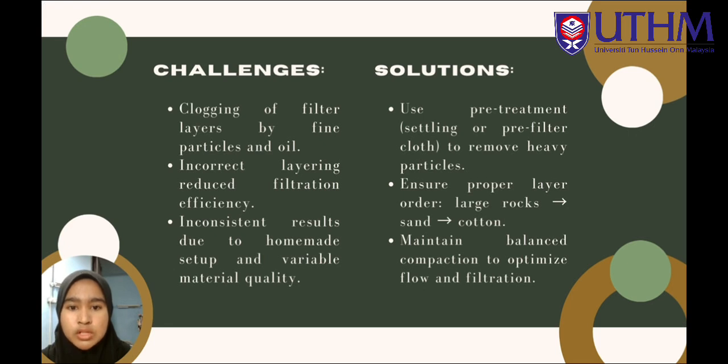To overcome these challenges, we applied several practical solutions. First, we treated the muddy water by allowing heavier particles to settle before filtration. We also ensured the filter was layered correctly, starting with large rocks at the top, followed by smaller stones, fine sand, and finally cotton at the bottom. Proper packing of the materials helped control the water flow and improved filtration efficiency. These adjustments allowed us to optimize the process despite the limitations of a simple setup.